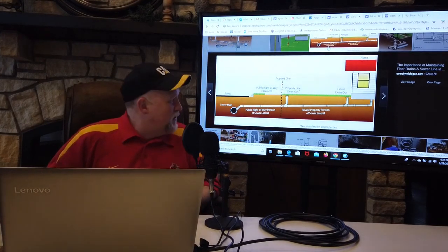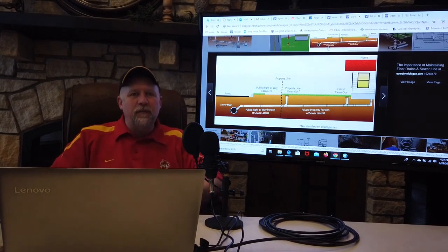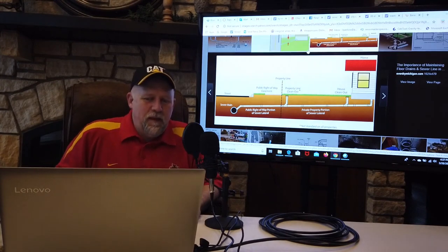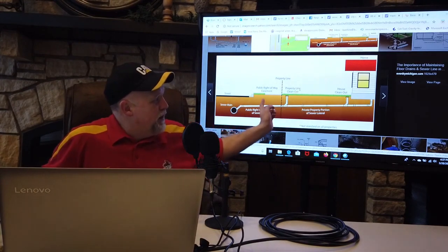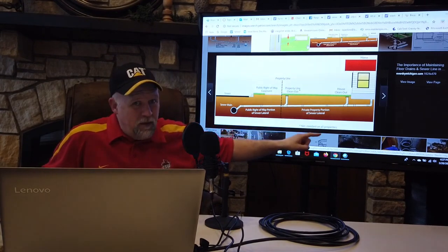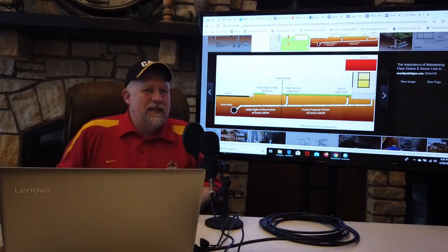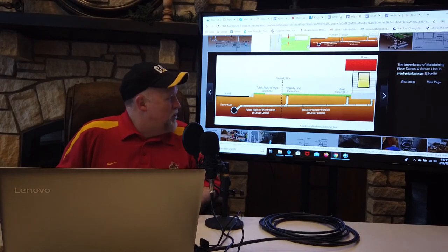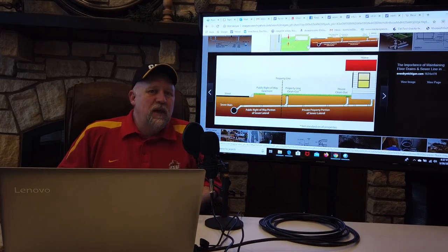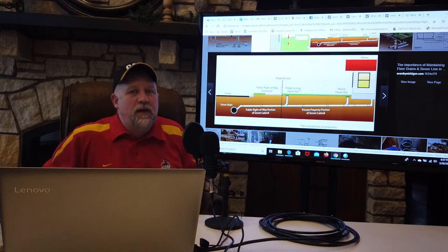Now, the steeper the slope that you get on this pipe, the smaller the pipe could potentially be. But also notice something else: the further back from the property line the building is, or the deeper a basement or something along those lines might end up being, the greater the chance that you're going to have to make that pipe flatter and flatter. In other words, less and less slope just to be able to meet this connection here at the street.